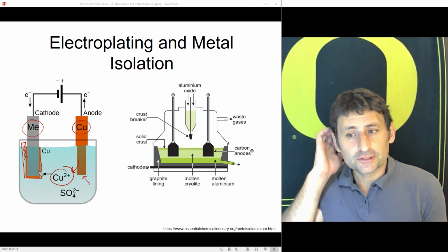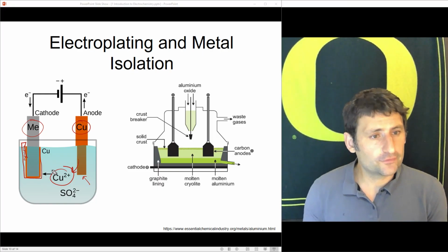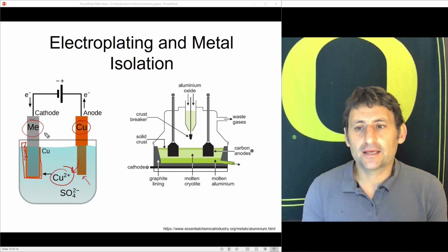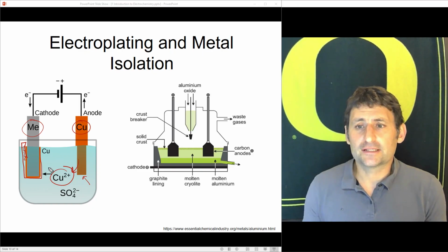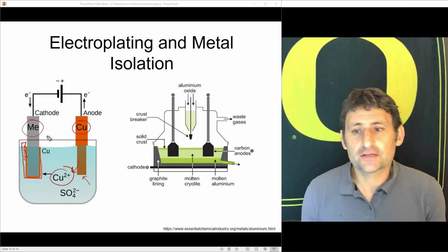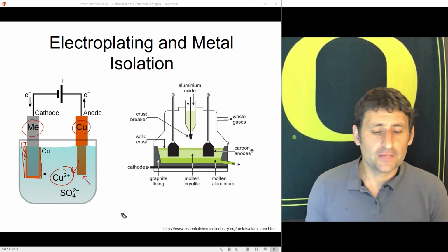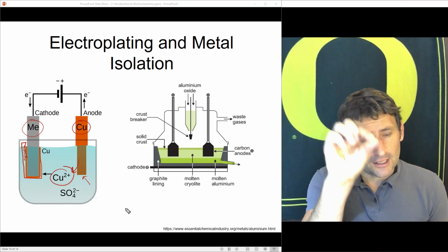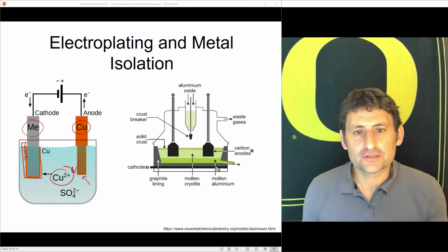So I can build a plated thin film, and this is useful for protecting the surfaces or endowing a metal or plastic even with the properties of a thin film of a more expensive metal. So this is used quite often for that. It's actually used in the manufacture of CPUs. They use the electrodeposition to deposit the interconnects that connect all the components of the CPU together.